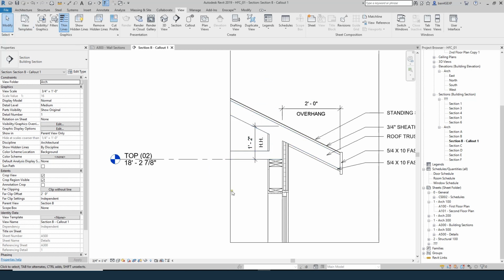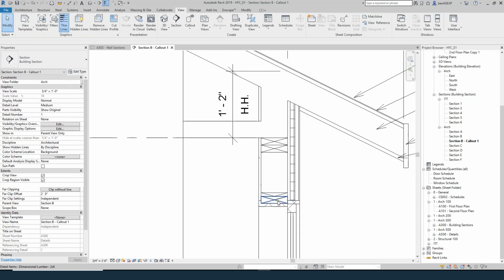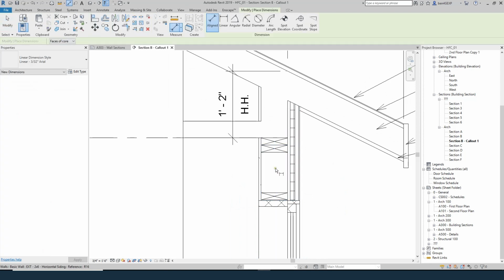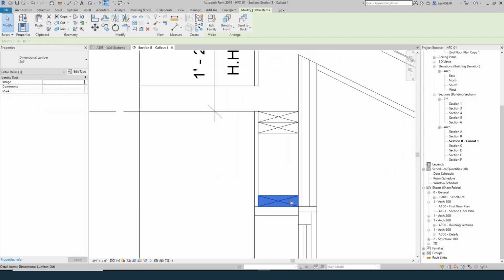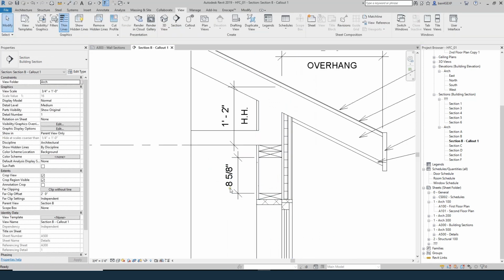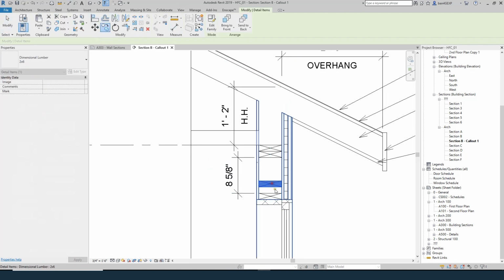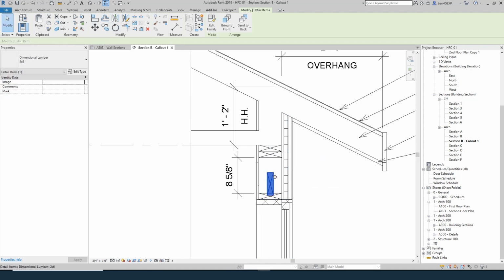We can also add in a header, which we haven't really talked about sizing, but we have left basically in between. This blocking right here represents some wood you're going to need to frame the window in. That's your double top plate. I've got 8 5/8 inches left, so I could use basically a 2x8 header if I need more. If I need a stronger header, I could use an LVL. I could integrate the header with one of either of the window framing or the double top plate. We'll just say that a 2x8 is going to be good enough for now. We'll make it a triple.